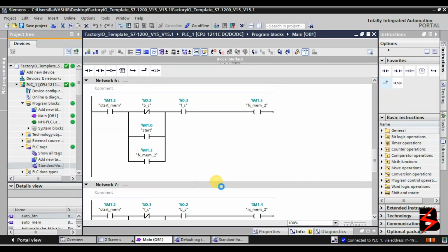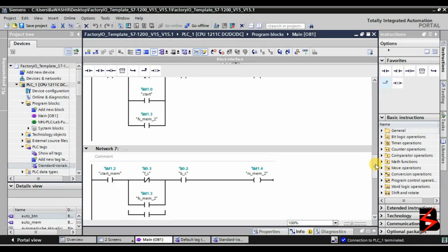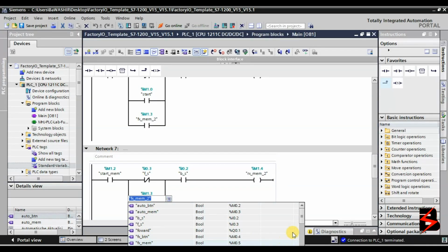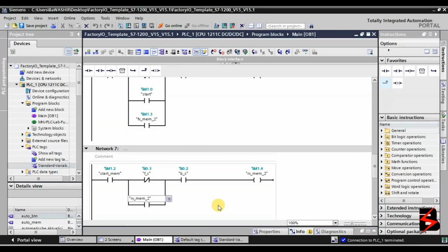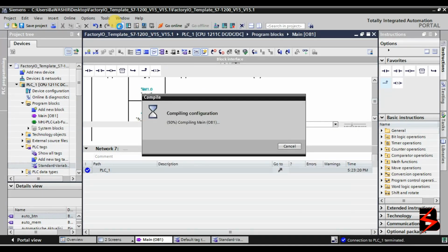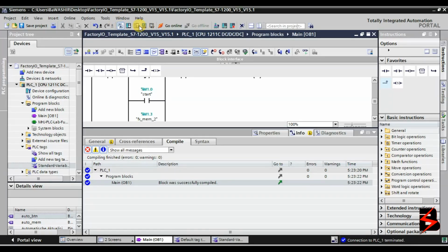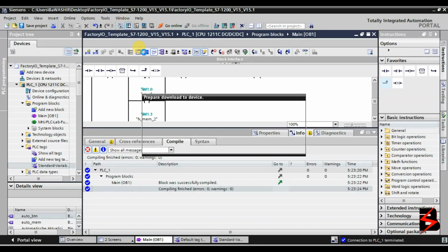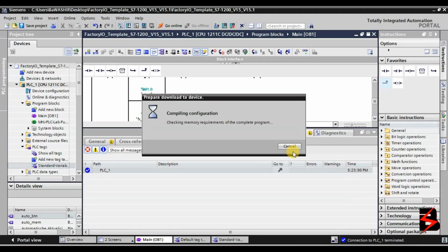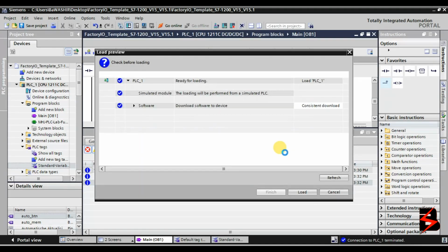Say yes. Then after going offline, now here, this is how we troubleshoot circuits. You can do this even when the machine is in run mode. Come here and select RX instead of FX. That's why I don't like jumping anything, so that you can follow properly. From there, you have to compile afresh. Then from there, you do download to device. Then there you say load.